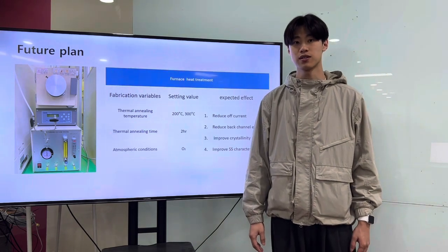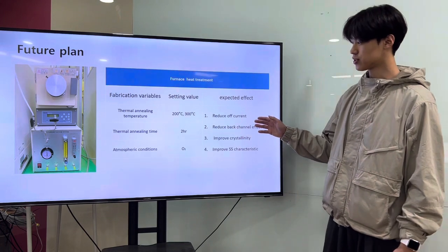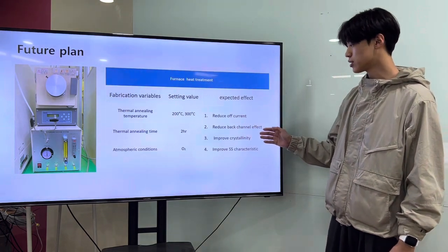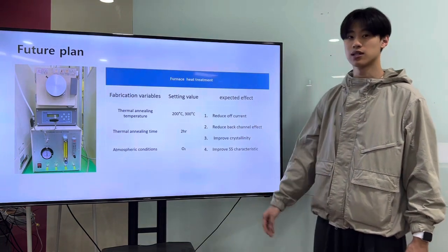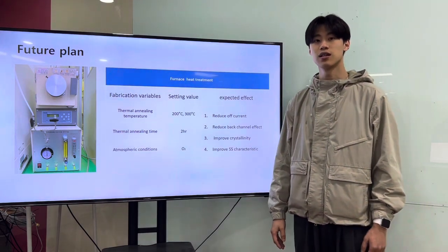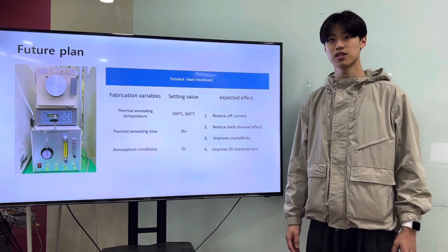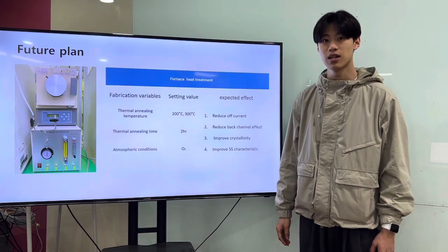The expected post-processing effects are: first, reduce off current; second, reduce back channel effect; third, improve crystallinity; fourth, improve sub-threshold swing characteristic.